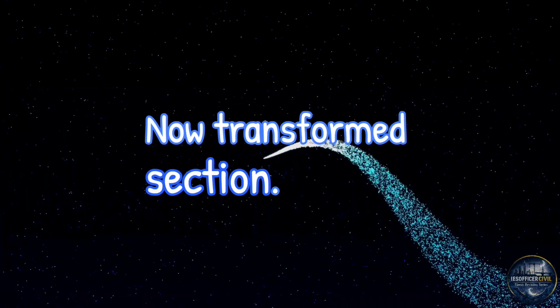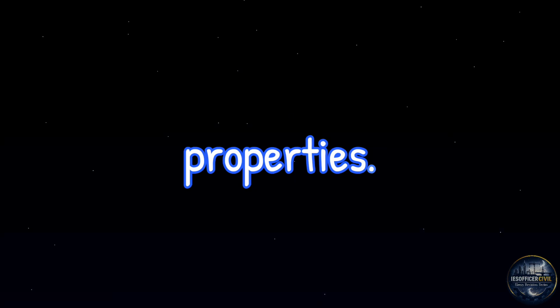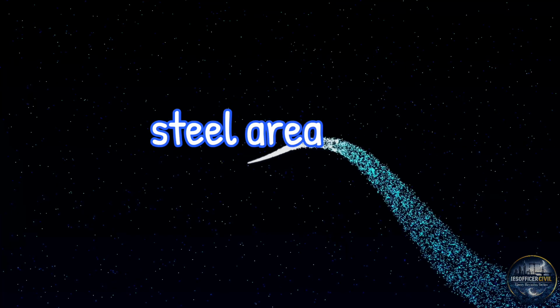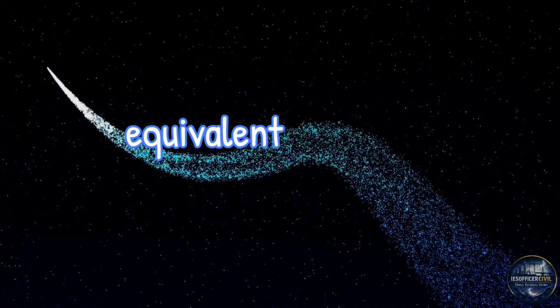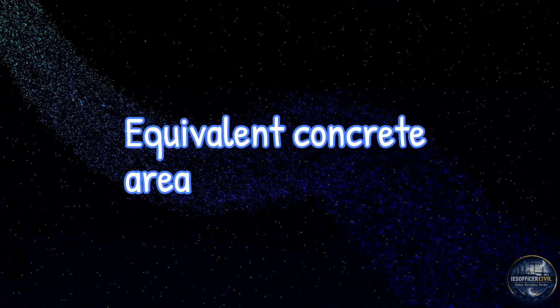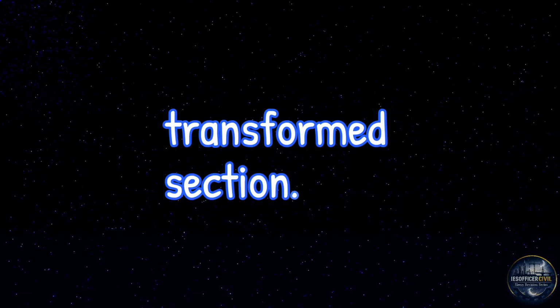Now transformed section. Steel and concrete have different elastic properties. To simplify analysis, steel area is converted into equivalent concrete area. Equivalent concrete area equals m multiplied by steel area. This converted section is called transformed section.